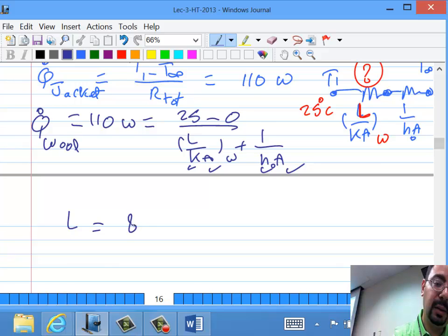Look at that. So rather than, what did we used to have? We actually had 0.15 millimeter thickness of this fabric, but actually 5 of them. Okay, but 5 times 0.15, that's not even 1 millimeter, right? And you have to replace it with 8 millimeter of wool. Why is that? Because of the air. Because actually you depend on the air to kill your heat transfer. All right?